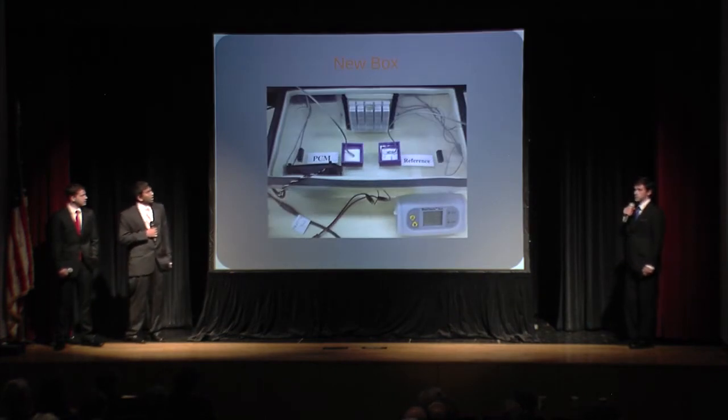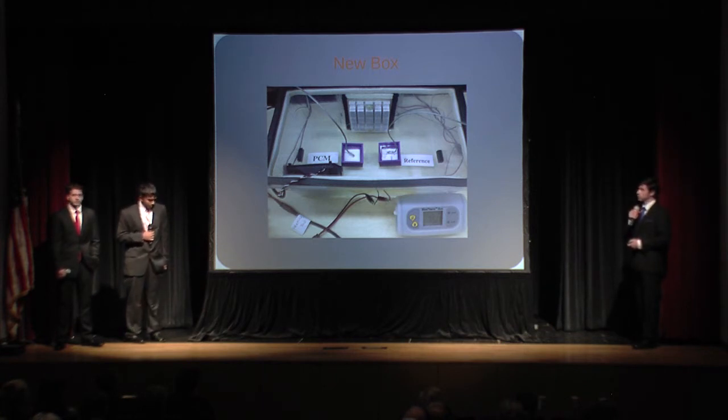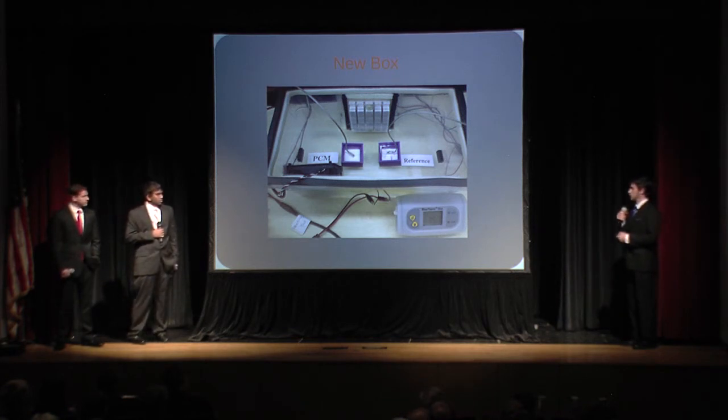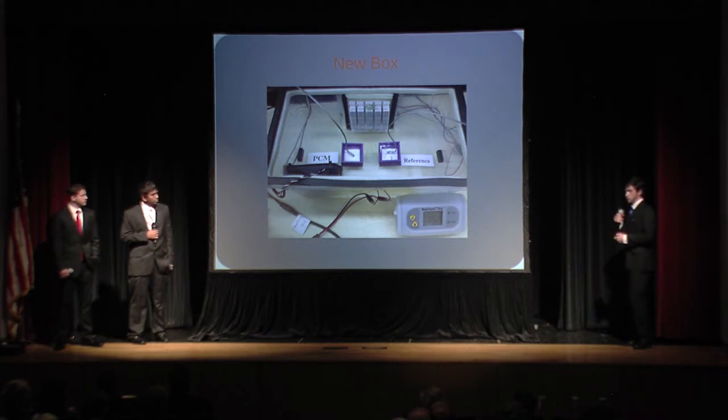Since the first box test didn't work because the room was warmer than the phase change point of the phase change material, we developed a new box which would allow us to cool down the area, to get it below the melting point of the phase change material, and then heat it back up with the heating pad so we could see what the phase change temperature was.